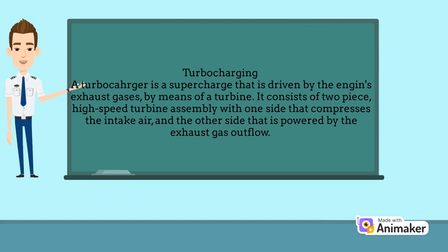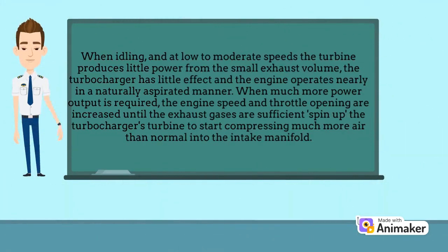Turbocharging. A turbocharger is a supercharger that is driven by the engine's exhaust gases, by means of a turbine. It consists of a two-piece, high-speed turbine assembly with one side that compresses the intake air, and the other side that is powered by the exhaust gas outflow. When idling, and at low to moderate speeds, the turbine produces little power from the small exhaust volume. The turbocharger has little effect and the engine operates nearly in a naturally aspirated manner.